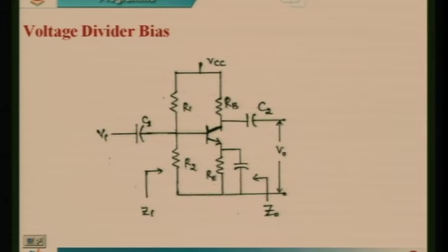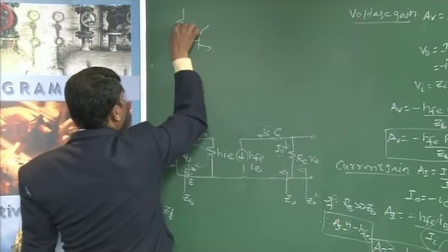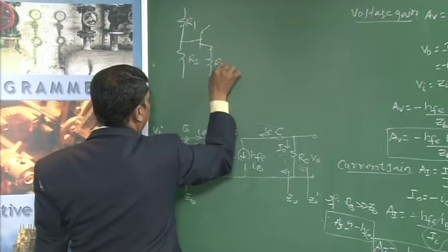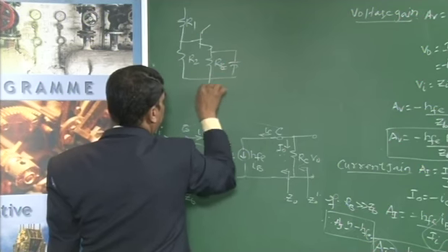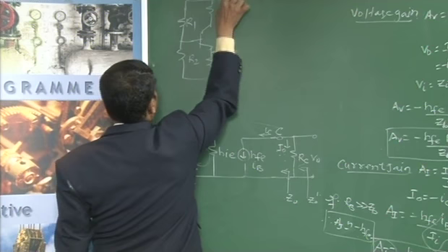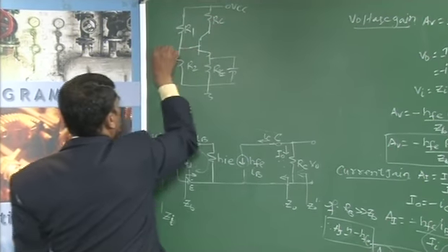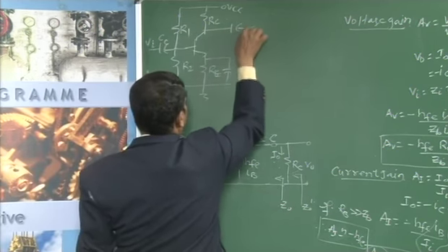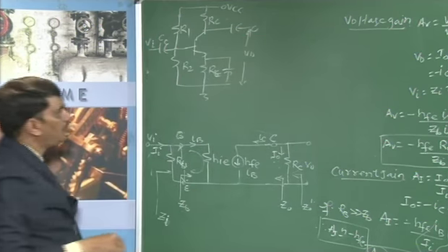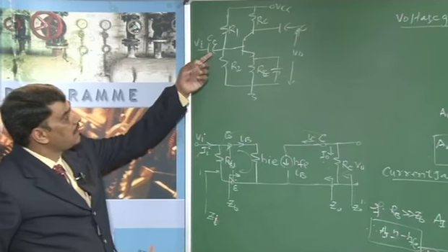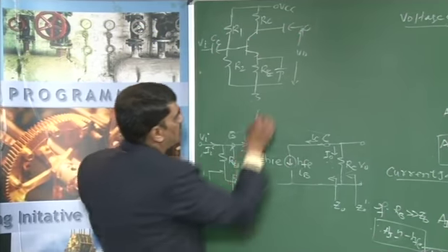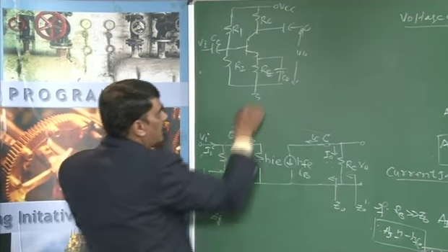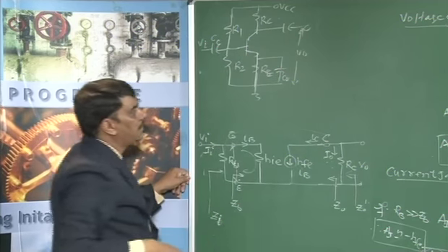In this circuit we have R1, R2, and RE in parallel with CE, and then RC is connected to the supply voltage, the input voltage is connected through the coupling capacitor, and the output is taken across the collector. At small signal frequencies, the reactance of a capacitor is very low, so the capacitor acts as a short circuit, and the emitter is connected directly to ground.